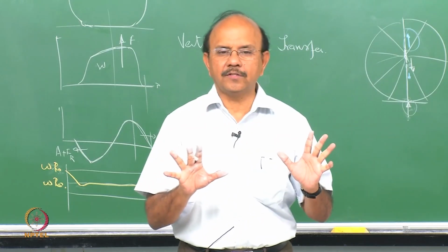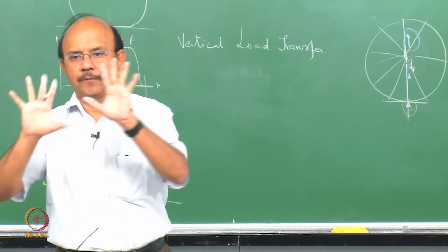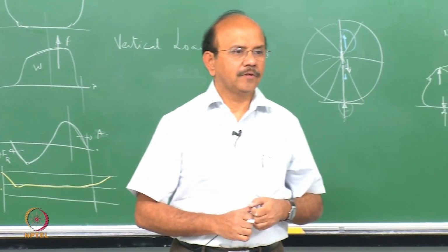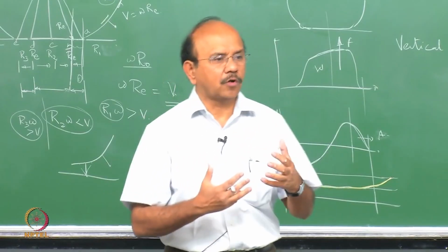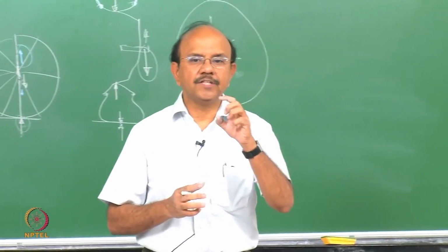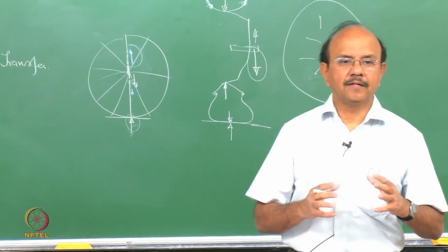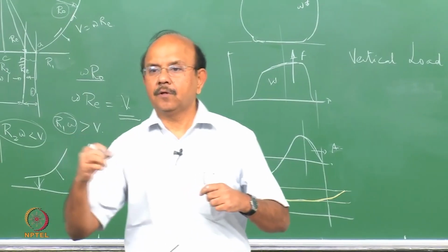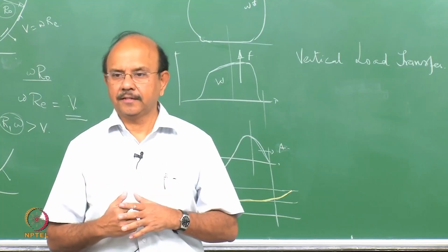What is meant by ground velocity? We said that we can treat the motion of the wheel as if the wheel is stationary and the ground moves in the opposite direction. So it is the difference between these two that would cause an extension or a compression of these tread elements. It's very important to understand that the tread elements can be extended in either direction.